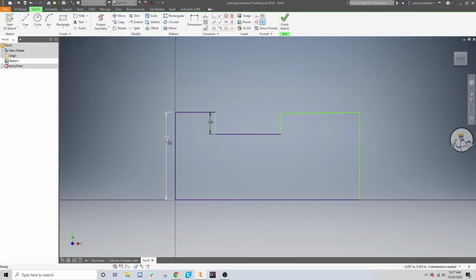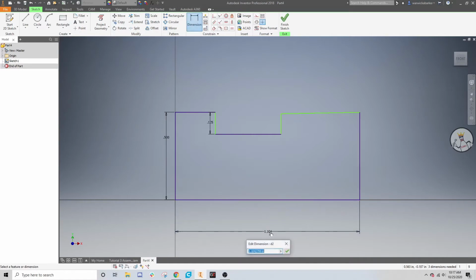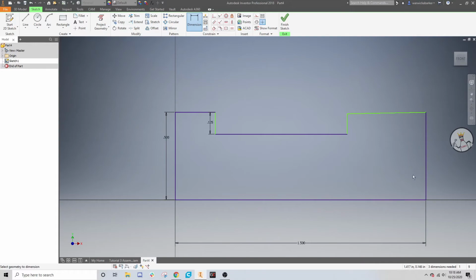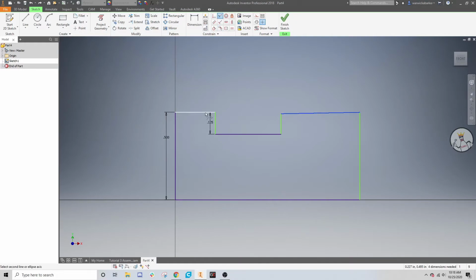And then if one has a dimension, it will be that height, because basically blue lines mean you can't change that line. But obviously this line's blue, but basically you can change it because you can make it longer. But that was because this line over here was green. Let me go back and show that. This line's green, so you can still edit it. Show this collinear again. There it is.